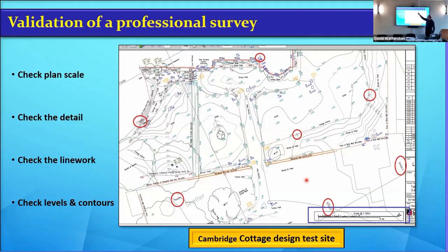And there's a plinth down this side that's broken off. If you've not got a DPC, it's generally at the top of the plinth. Because the idea is, they didn't want any water to seep in underneath or above it. So any rainwater coming in would run off the top of the plinth and not in. So it's broken off, but if you look at where it's broken off, it's almost the same as the floor level, and it's more or less within 10 mil of the damp-proof course that they put on when it was built. All right, and that can be a useful level datum as well.